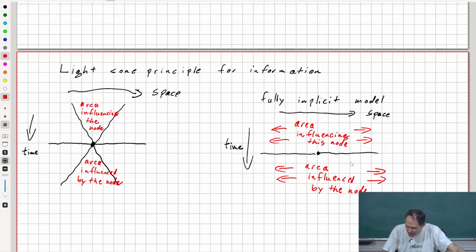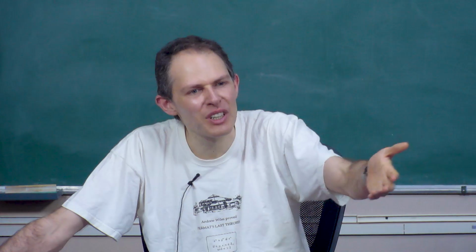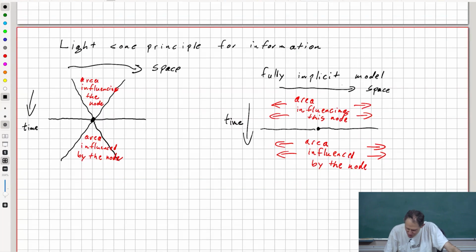So, solving the Navier-Stokes equation, can somebody tell me where you have this fully implicit problem? Incompressible Navier-Stokes equation. You are nodding. No, the speed of sound would be infinite when we're talking about solving the incompressible Navier-Stokes equation. So when you solve the incompressible Navier-Stokes equation, you would have to come up with an equation for the pressure, right? And the equation for the pressure that you would usually solve is the pressure-Poisson equation.